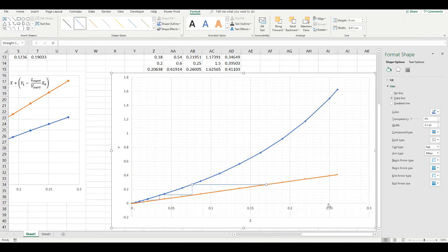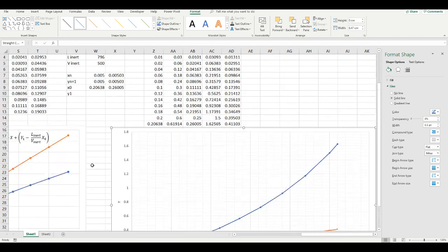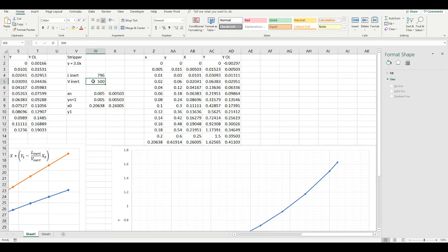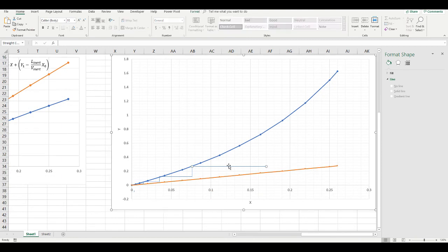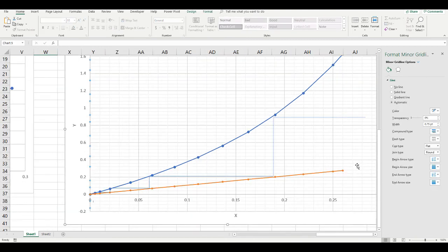Okay, so now we've drawn the McCabe lines with 500 moles per day, and we can see that with 4 equilibrium lines we don't get to the end yet, so that means that 500 is too low. So let's choose another value. Let's choose 750, so a value in between both of these, and let's see what we get. Okay, so now we've traced another 4 equilibrium stages. With this flow rate, you can see that we're above the operating line after 4 stages, so we need to go a bit lower.